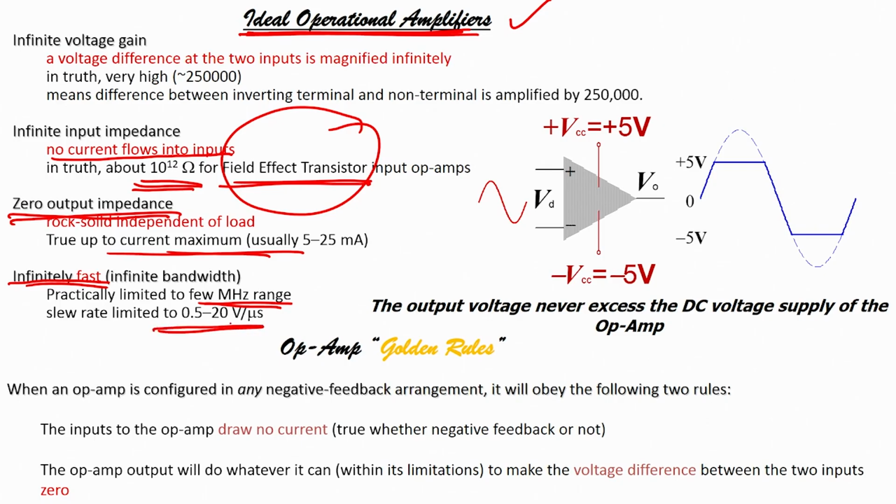By understanding the slew rate, that means if I apply the signal at the input, can I also see the corresponding change in the output simultaneously? It has some lag. So, what is that lag? How fast my op-amp output can track the input, right? That will be given by the slew rate. I will show you the slew rate also later on.